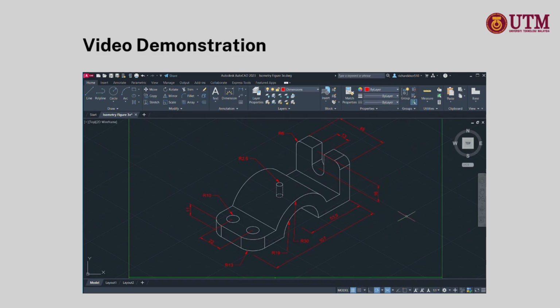Finally, inside a general engineering drawing, tolerances should be mentioned as well. In this case, it isn't mentioned, but along with the legends stated earlier, another legend for tolerances should be included. This is to allow variation in size to help control quality and function. So that will be all for the dimensioning standards part of the AutoCAD drawing.